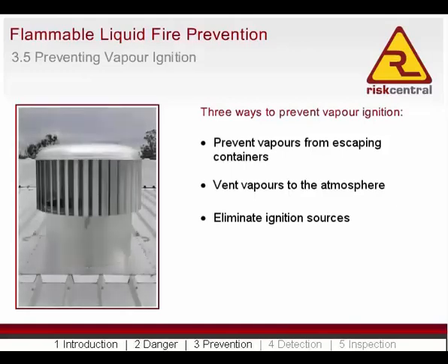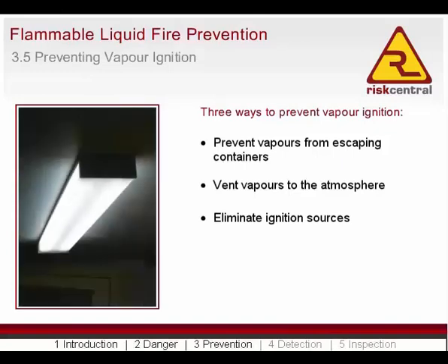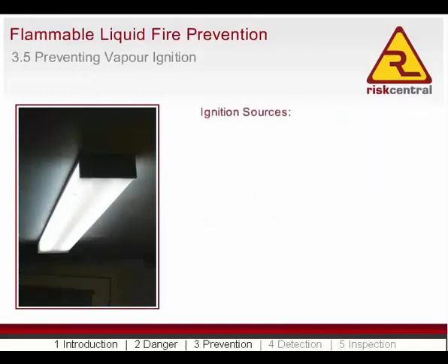You should always ensure appropriate ventilation before starting to dispense or open containers of flammable or combustible liquid. For this reason, appropriate ventilation is very important in flammable liquid storage sheds, rooms, or any other area where vapours could exist. Vapours may be heavier than air, so low-point ventilation is also important. Because vapours can travel long distances and are easily ignited, just about anything which can produce a spark or heat can become an ignition source.